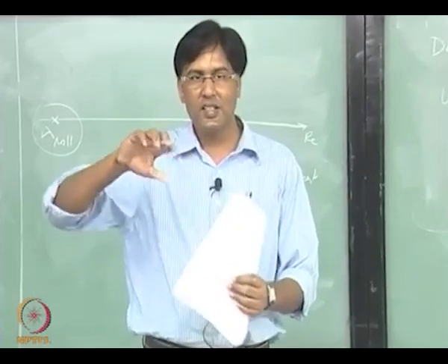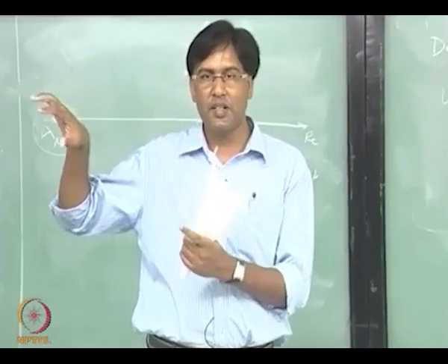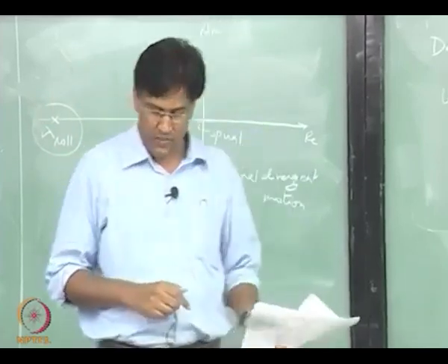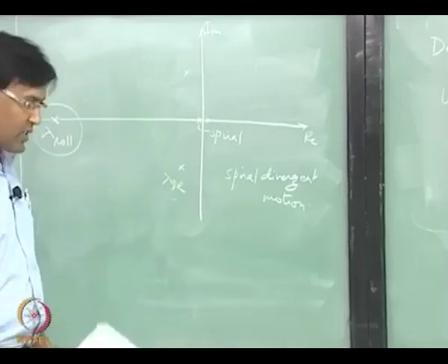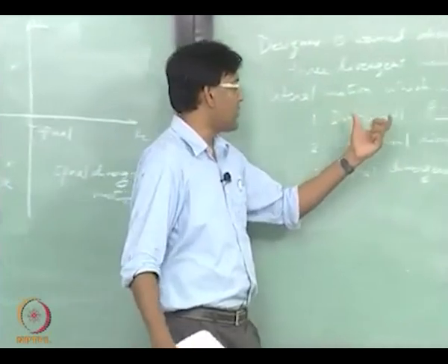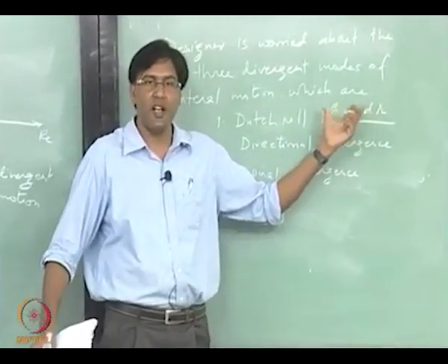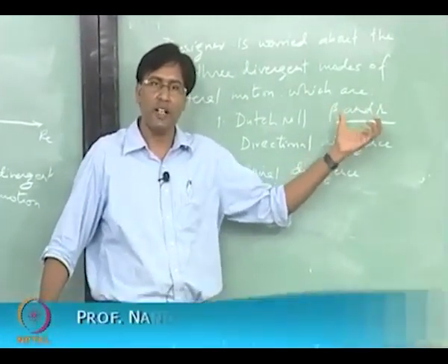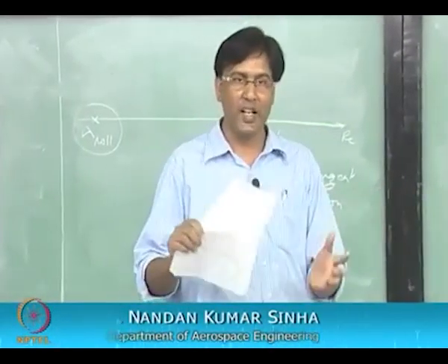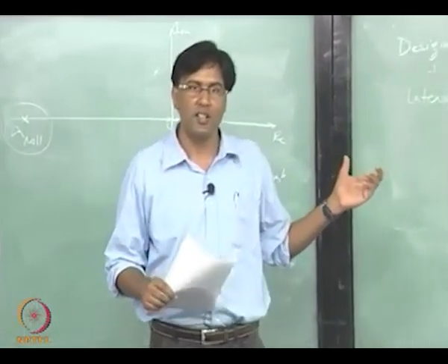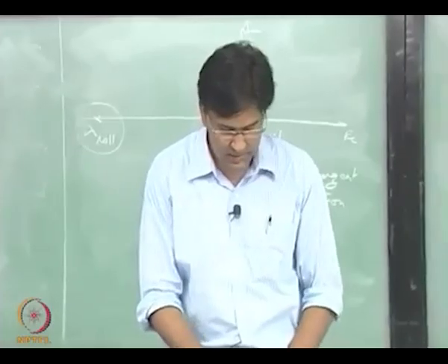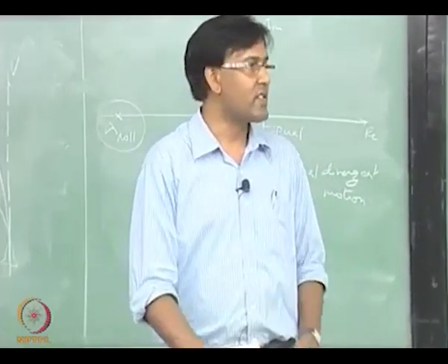So it looks like the wing tip of the aircraft is making some closed curve, which we observed this time. So when you now make the assumption that it only involves beta and r, and then arrive at the approximate formula, you will find that the formula is not really correct. There is some amount of roll involved, okay, and that we will discuss in the next class. So we can stop.